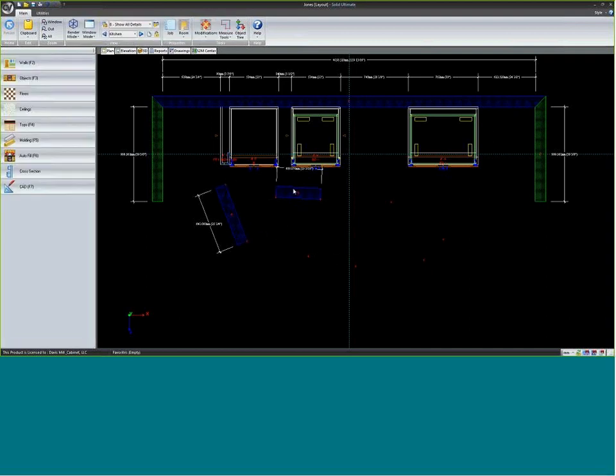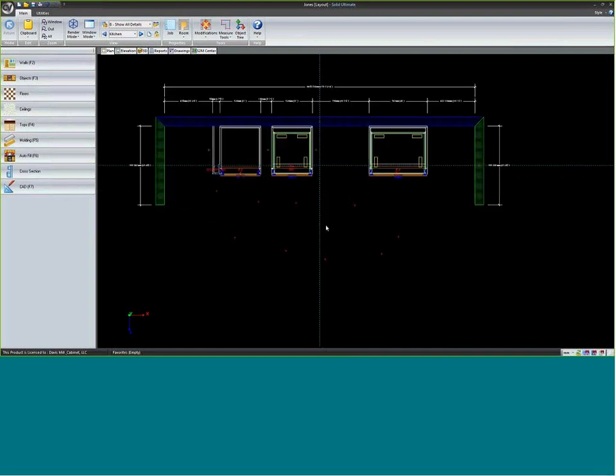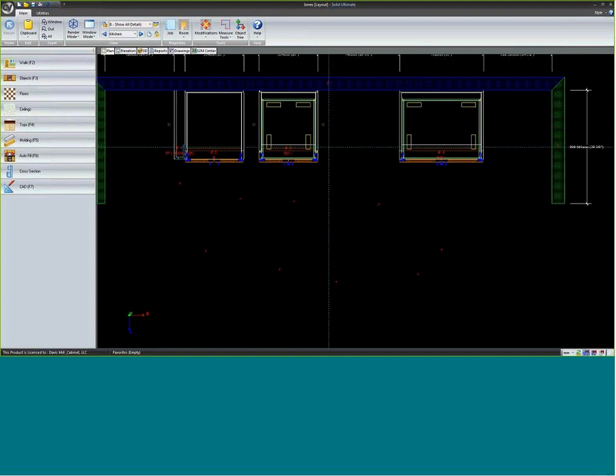You're not going to put walls like that in the middle of a room, but the idea of these is a way to snap floating locations for your walls to be located. Notice now I zoom in and out and those red points are there. That's because my snap to marks mode is on. If I move my mouse away from it, you should be able to see a little bit of a blue highlight to that tool. If I click on it again, it turns off the blue highlight, turning off the tool. Snap marks also disappear. They're just hidden.